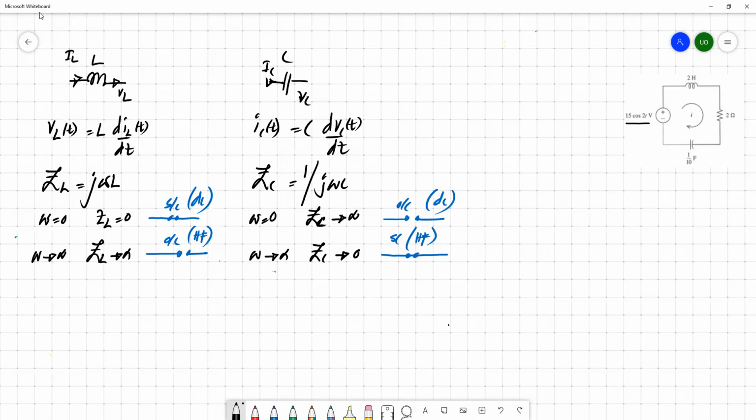So then we can claim that for this case, in the phasor domain, the voltage is perpendicular to the current. VL is actually omega L Im, with an angle of pi/2. Always we have pi/2. Similarly for the capacitor, this is your VC, Em, angle of 0. So the other way around.